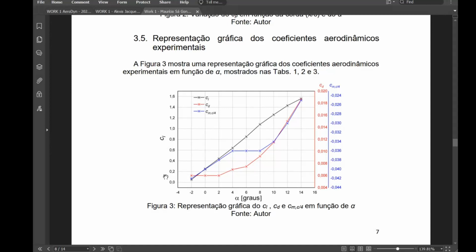Why is it made like this? Because lift coefficient and drag coefficient have very different scale. As you can see here, maximum of lift coefficient is 1.6, but for drag coefficient is 0.02. So much different, around 100 times, right? Oh, less, okay, 60 times more or less. Since they are different, you cannot use the same axis for lift, drag coefficient, and momentum coefficient. I recommend you to use 3 different axes on the same layout.